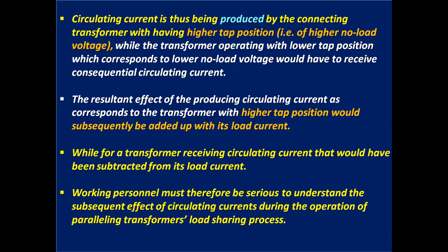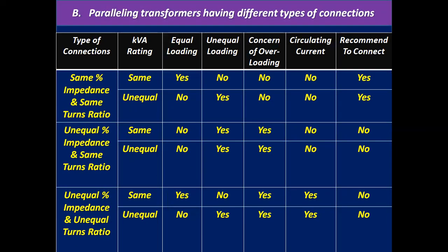Working personnel must therefore understand the effect of circulating currents during the load sharing process of paralleling transformers. Now, paralleling transformers having different types of connections, kVA rating, equal loading, unequal loading, concern of overloading, circulating current, and recommendation to connect.